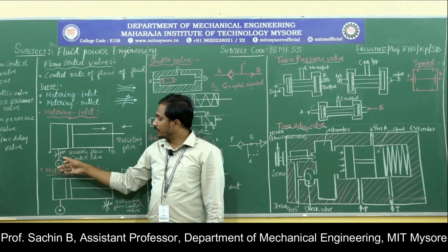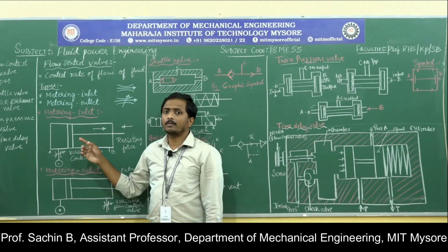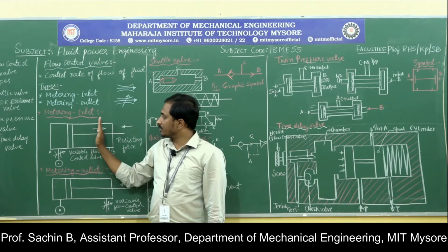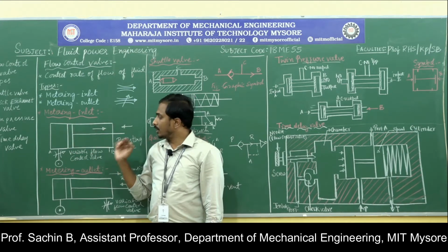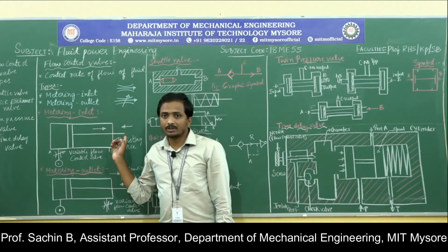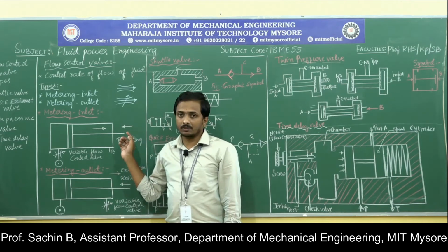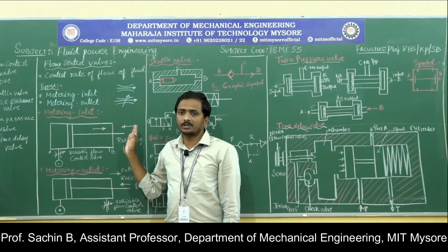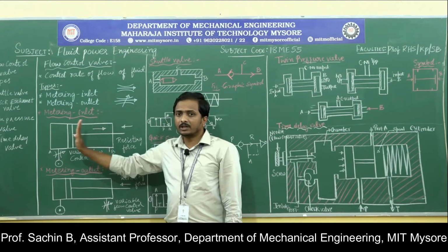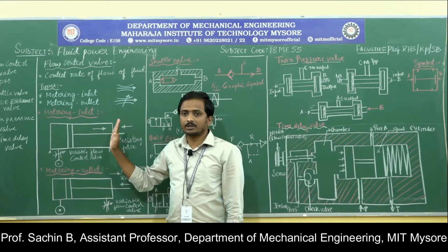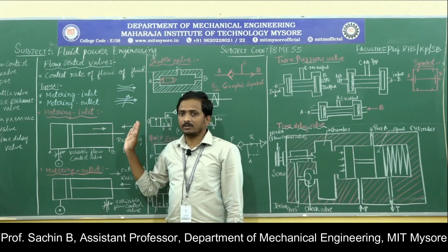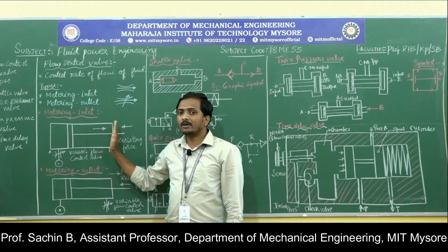For that purpose we are metering at the inlet port, meaning the smooth extension of the cylinder to the tail end. You can observe that a resisting force will be there, connected to this piston. It is doing some other operation or lifting a load, meaning some force will be there, but we don't require fast movement of the piston, fast lifting of the load, or fast movement of any operation. We require only the smooth movement of the operation.